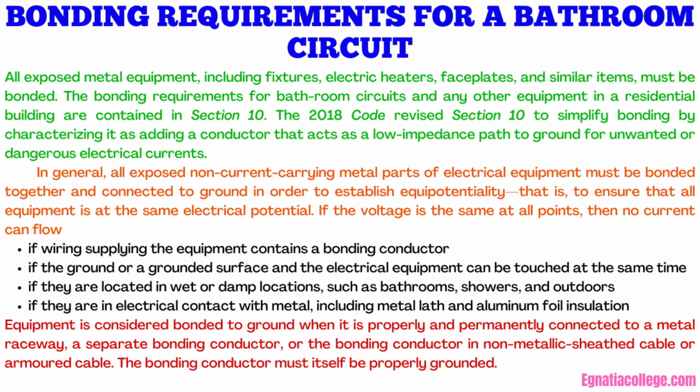If the ground or a grounded surface and the electrical equipment can be touched at the same time. If they are located in wet or damp locations, such as bathrooms, showers, and outdoors. If they are in electrical contact with metal, including metal lath and aluminum foil insulation.